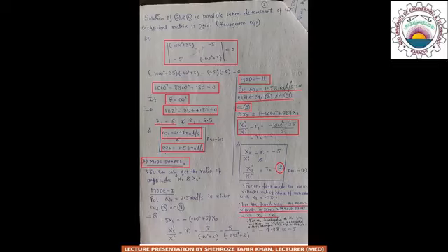So in this step, we found the ratios of the mode shapes for the system at its two natural frequencies, but the values of the actual mode shapes still need to be determined, and for this purpose we will calculate the response of the system, at the end of which the actual values of the mode shapes of the system will be yielded.